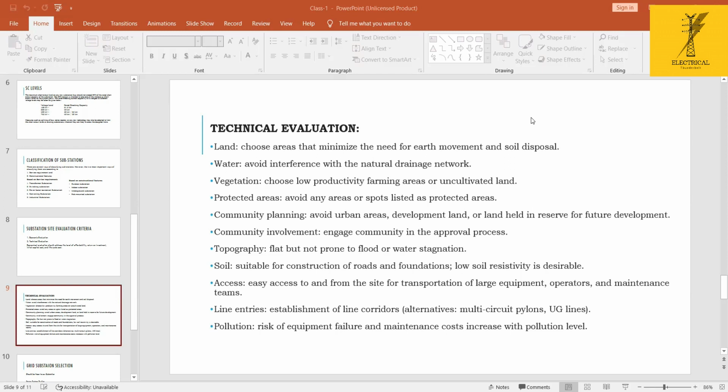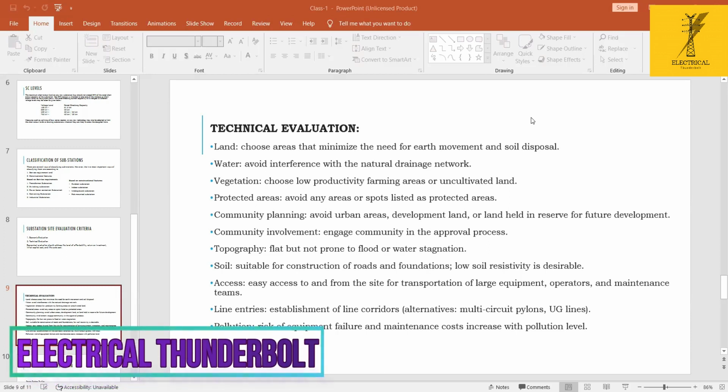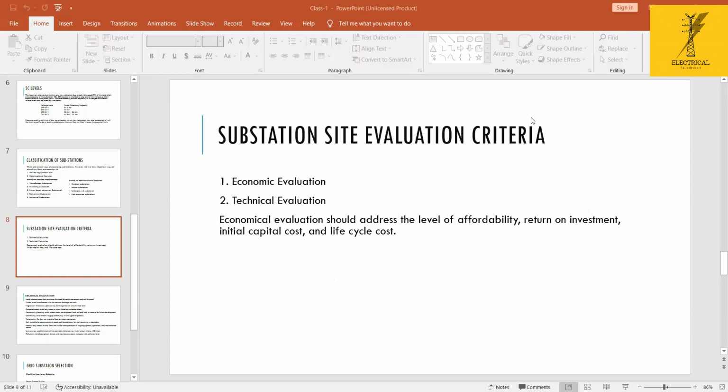Yes. See, generally for the earthing design, team, please mute your mics if you are not talking. We already developed the earthing design for our previous projects. In the earthing design, what are the main important factors influencing it? One is the soil resistivity, the other is your area. So already we have the design and the area. When we change the area parameters and the soil resistivity, we come up with the bill of material required for our earthing.